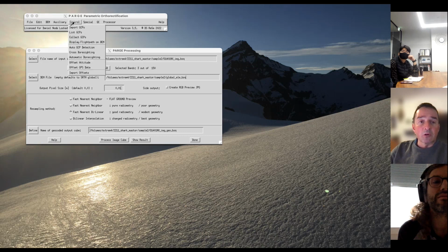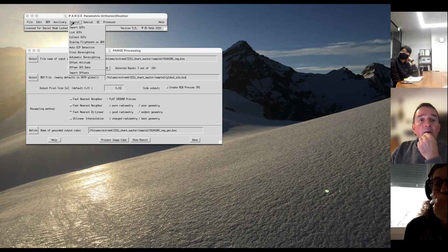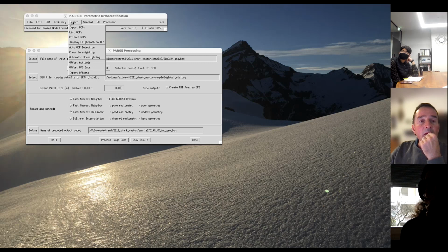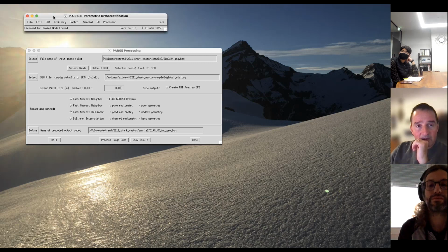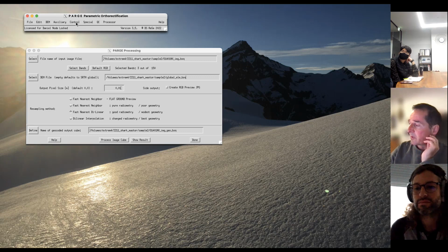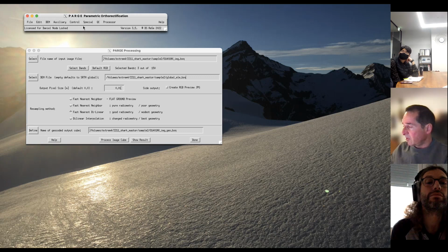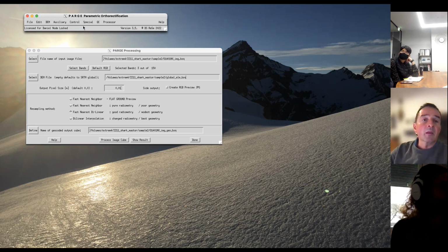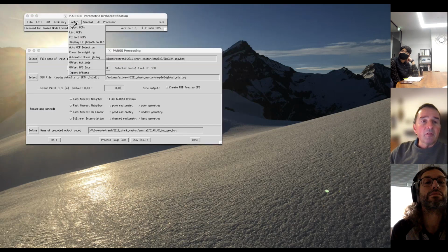Now I want to do the so-called bore sighting. Bore sighting means system calibration. So I want to calibrate it against a reference. And you provided an orthophoto from Pix4D. So one can use the orthophoto as a reference to, yep, I already have some GCPs to get it done.